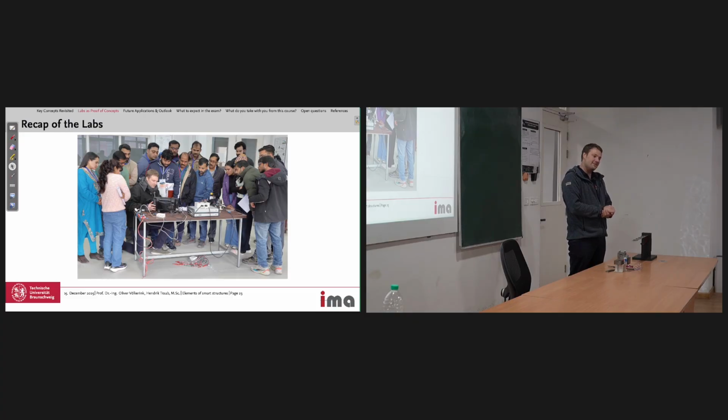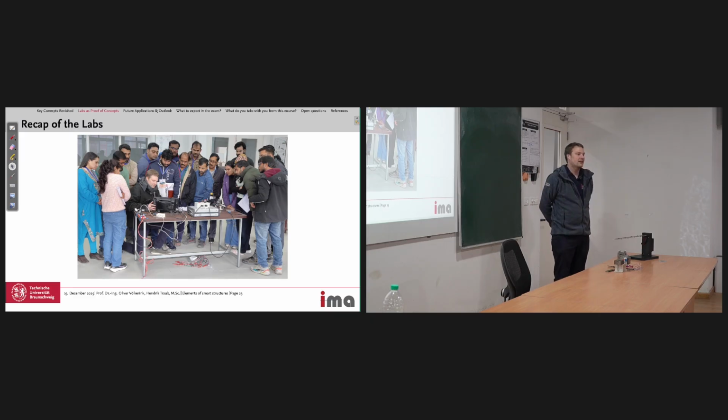And what I didn't tell you today is that this setup is not perfect. The eigenfrequency is actually a little bit higher, because if I hold it here, can you see how the beam shifts? Yeah, so it's not a perfect clamping, because this is not stiff enough, because it's plastic and not steel as it's supposed to be, but then steel was too heavy to bring. So actually the frequency would be a bit higher if that would be stiffer. Okay, so small mistake, but nothing which changes the principle of how it works.